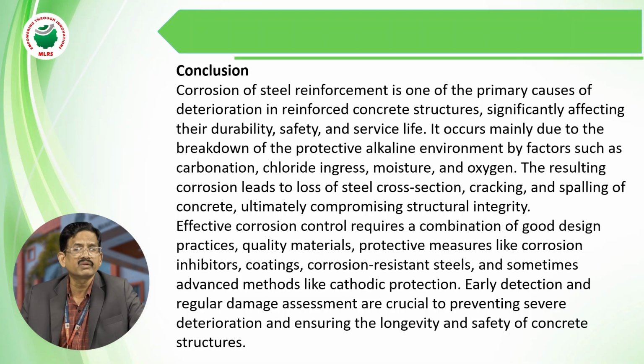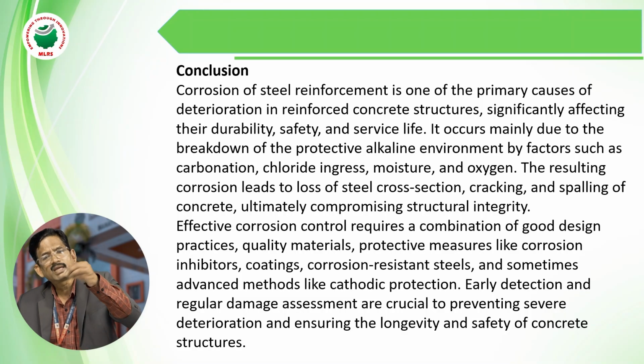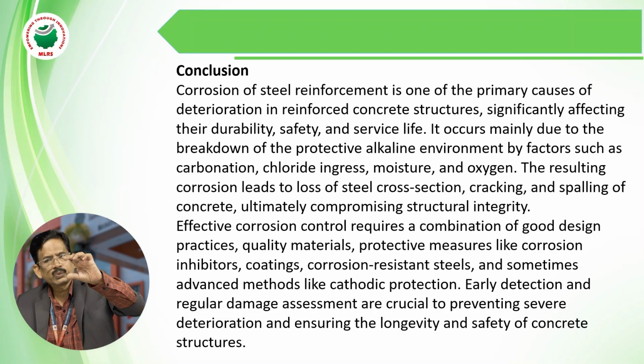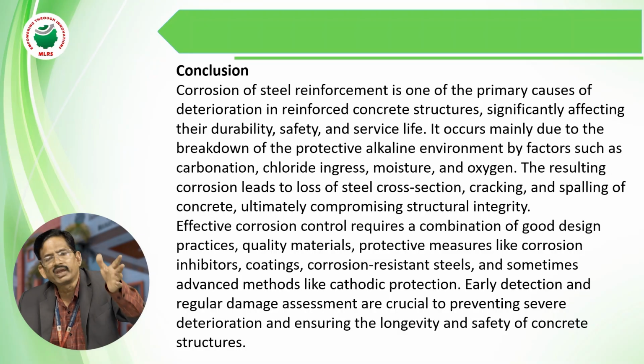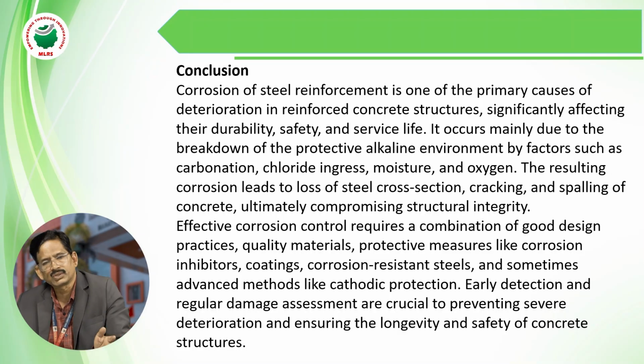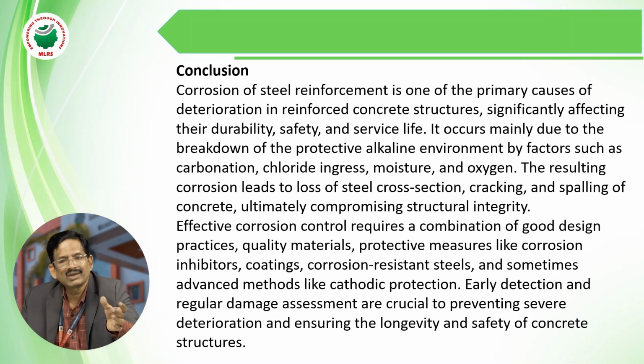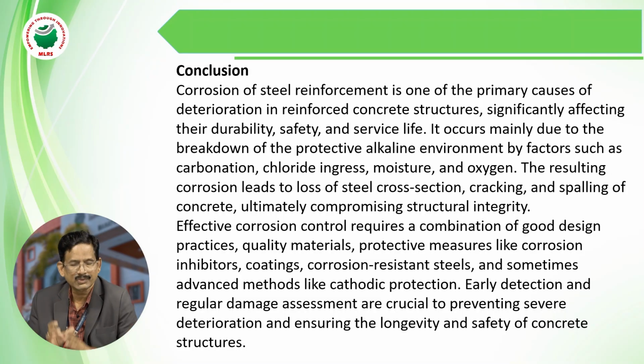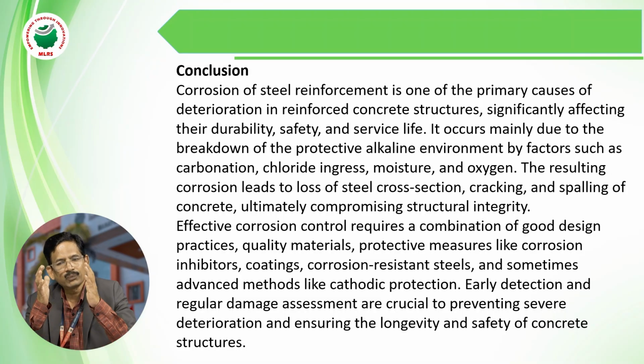Shuttering also plays a very, very important role in the corrosion of the steel reinforcement, as does providing the reinforcement in the proper way. We have to provide the clear gaps, how much gap between one bar and another bar, what is the clear cover to the beams, to the slabs, to the footings.